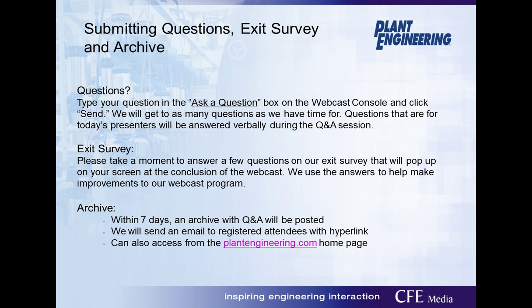Another great question. What I would do is first start with doing what we call a leak load as part of the baseline. So what does that mean? That basically means that when you go into your operations, if you have the ability to go in on a holiday where no production is being run, how much compressed air are you using then? Go through and look at what's being done. If you have a meter, put a meter on it. See what your flow is.